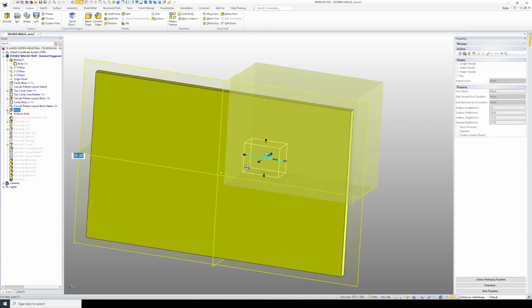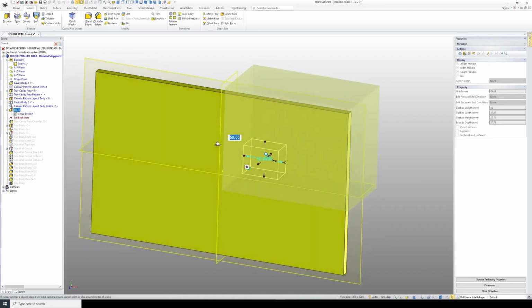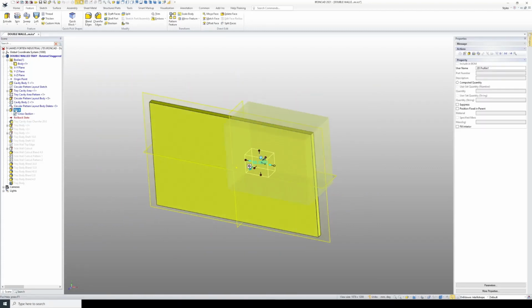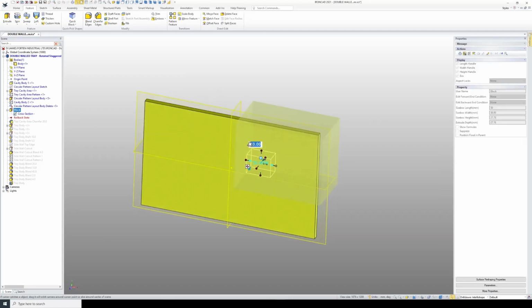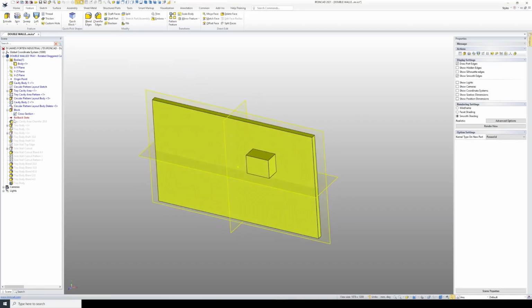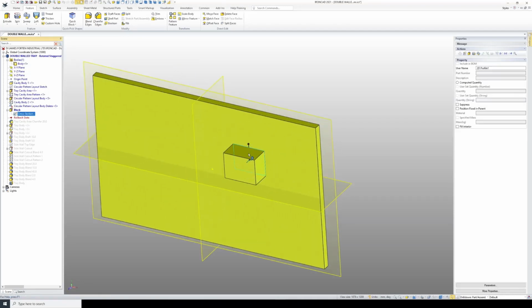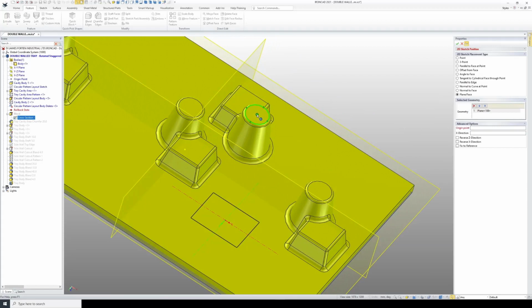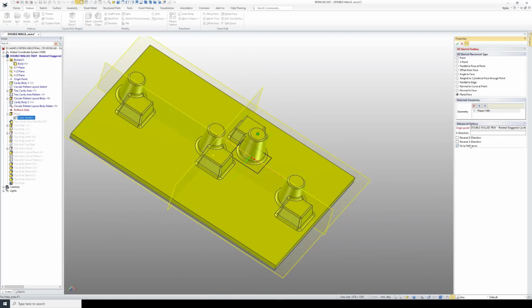And so in our scene browser here, we'll go to the sketch of, I'm just wondering what's happened to my display. Let's try recreate display. Oh yeah, that's better. So go to the underlying sketch of that block, and I'm going to constrain it. So edit the position. I want it on that plane, and that's where it is. But the origin point, I want that to follow the center of that patterned body, and the X, everything else, and I want it fixed to reference.